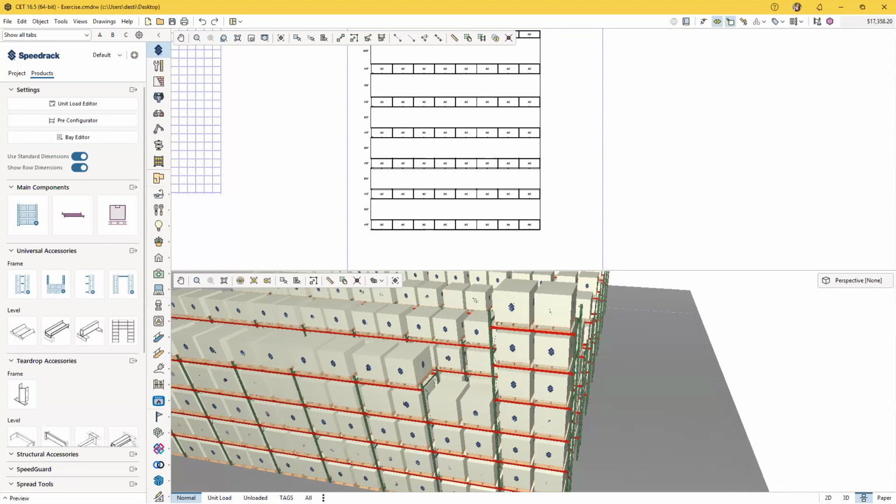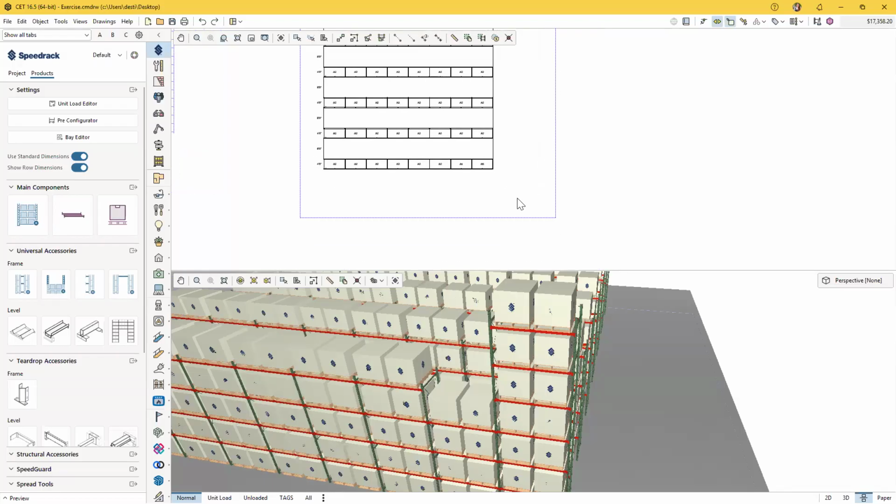If not, the way that's going to work the best for all of the other functions is to redraw the portion that needs to be moved back. So just delete the one that you had moved and then redraw a new portion. That will allow it to connect back together. Otherwise, you're going to have separate systems. It is workable that way. You'll just need to work with them individually from that point.